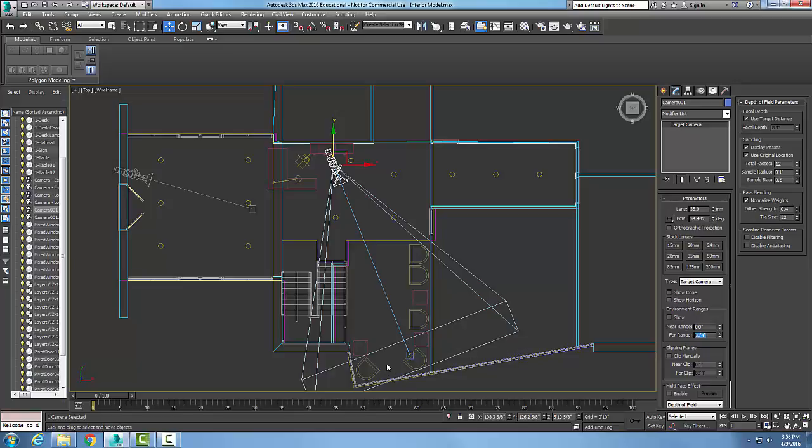So for example, I could have picked the camera to be at the first chair, and then I could say, I don't want to see these back chairs. And so we could clip those off if we wanted to. We could also do it for the near clip. If there's something up in the foreground that we don't want it to see, we can just Photoshop it out of there and set the distance further deeper, and it will clip those out of there. So that's what clipping is.